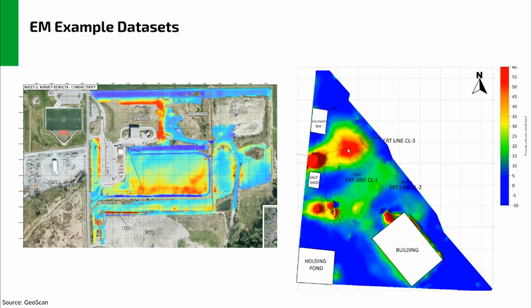That's a really important detail to share. Sometimes people forget and think that we can see contamination, and we can even give some sort of quantifiable data of what kind of compounds that might be, which is not true. What we simply can do is map out where the groundwater has increased conductivity.